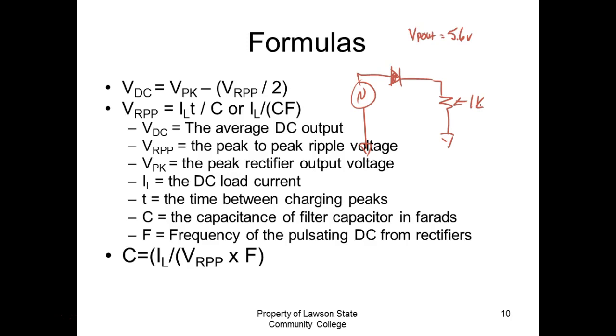Huh? Y'all haven't ever looked at y'all's power supply before? The input voltage, the output voltage, and the maximum current it should put out. So that's the two things you're looking at when you design a power supply. How much input voltage are you going to put into your transformer? How much you going to get out? And how much current that dang load is going to handle.